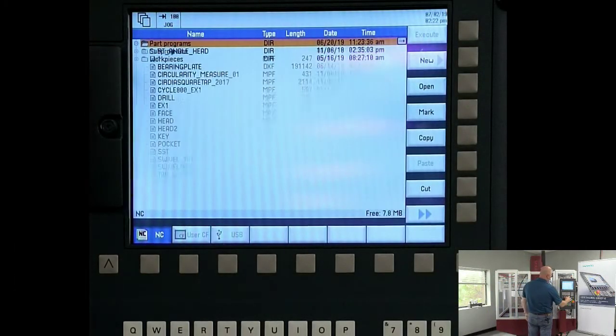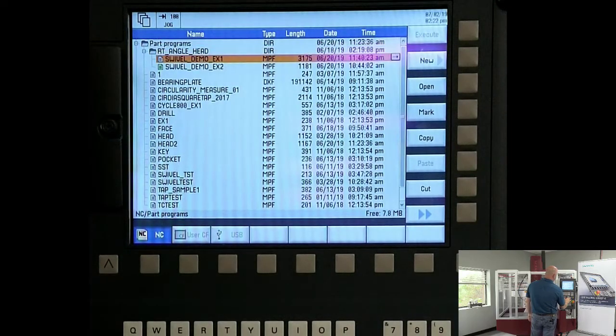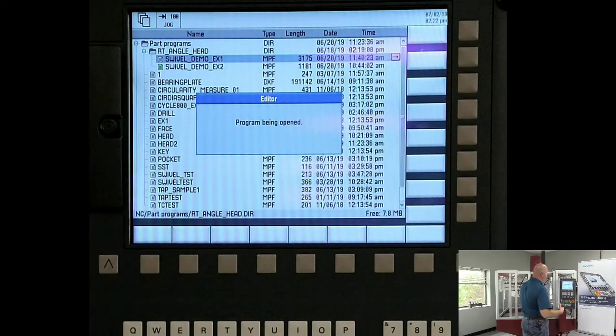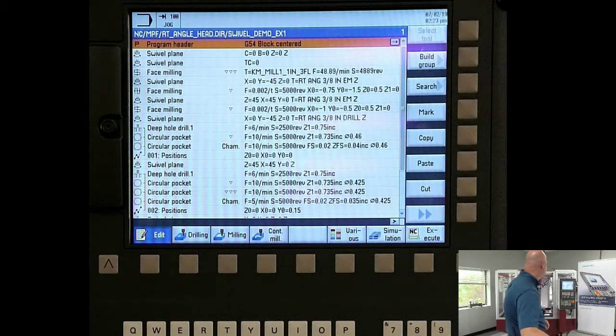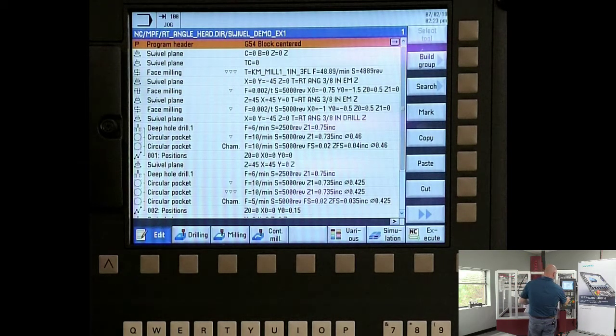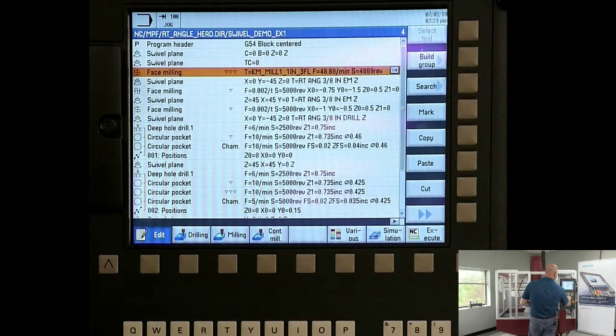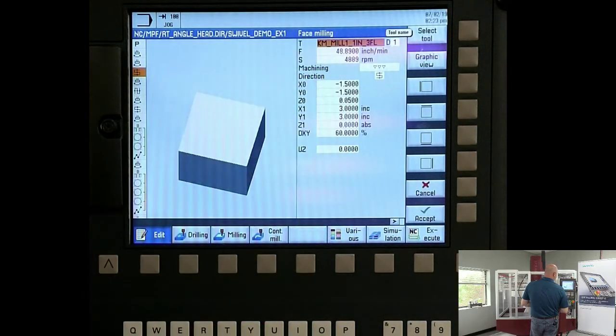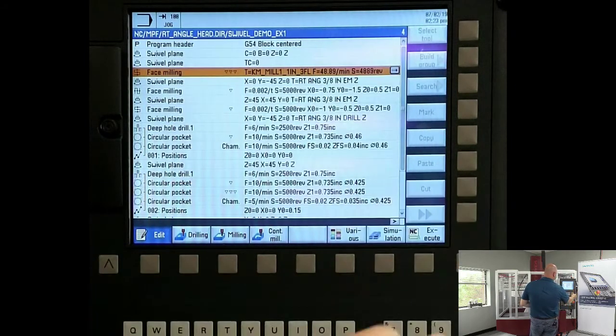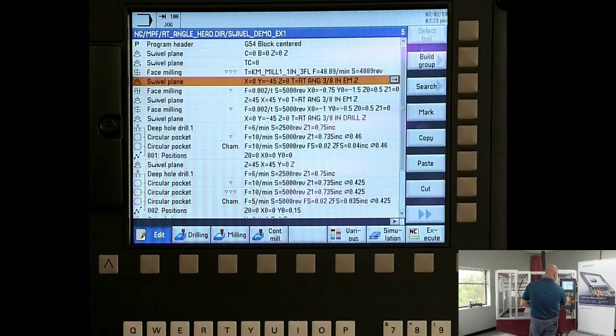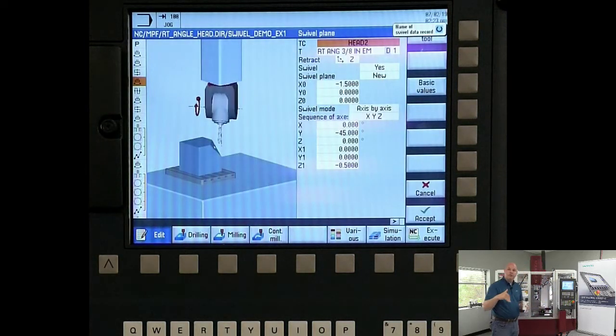I have a part program that I've created, and this is the full program. So this does all of the operations. It allows me to come in, switch between standard tools like my metal mill 1 instrument that I did a lot of the peripheral milling with, and then also use the swivel cycle to establish an orientation. I can move my zero around the swivel cycle.